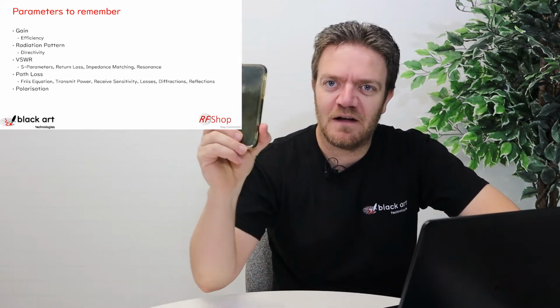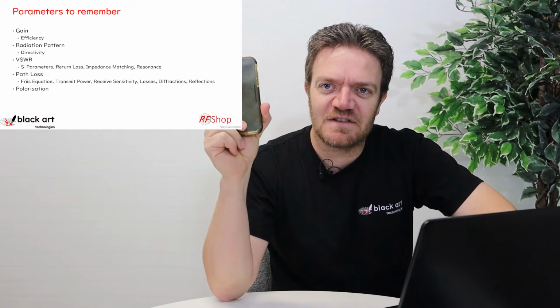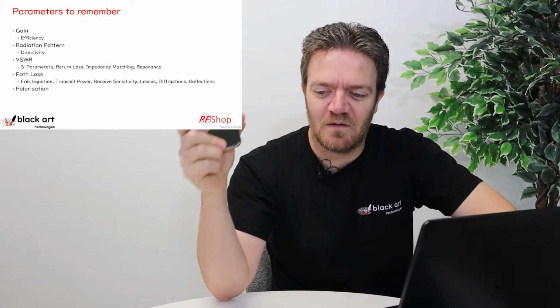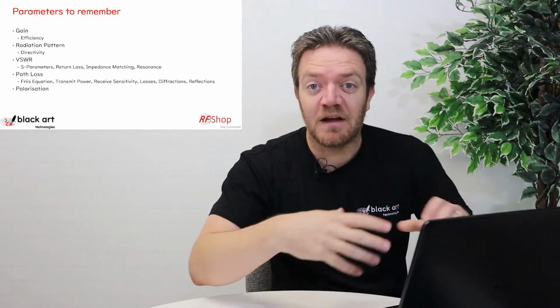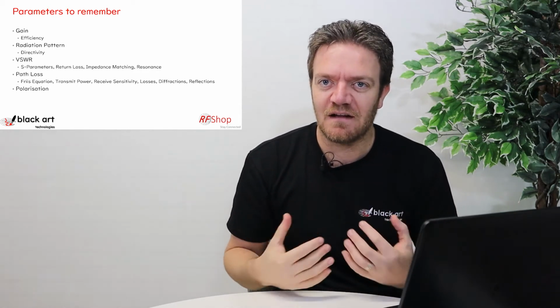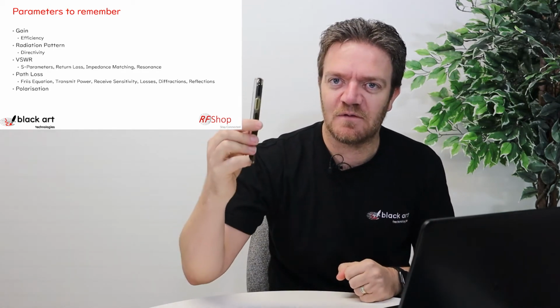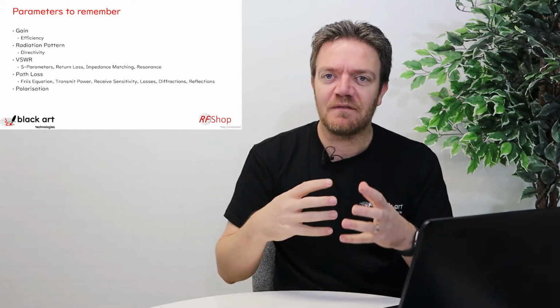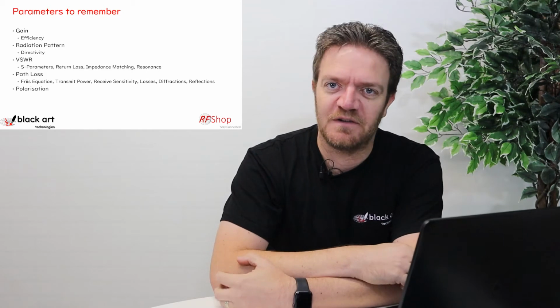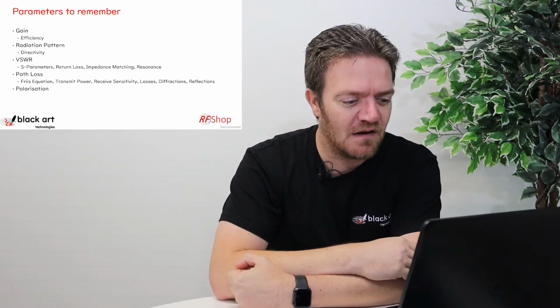So you can think, now I have my phone again. The base station, the further I'm away from my base station, the less I can hear what's going on. My phone is starting to struggle. By using the Friis equation and a bigger version of the same equation, you can see when you receive, you can calculate what you get and if that's enough or not, because the system can only hear so much and not more. If you don't have enough power here, nothing is going to happen, and then you need to do other stuff to try to fix that.